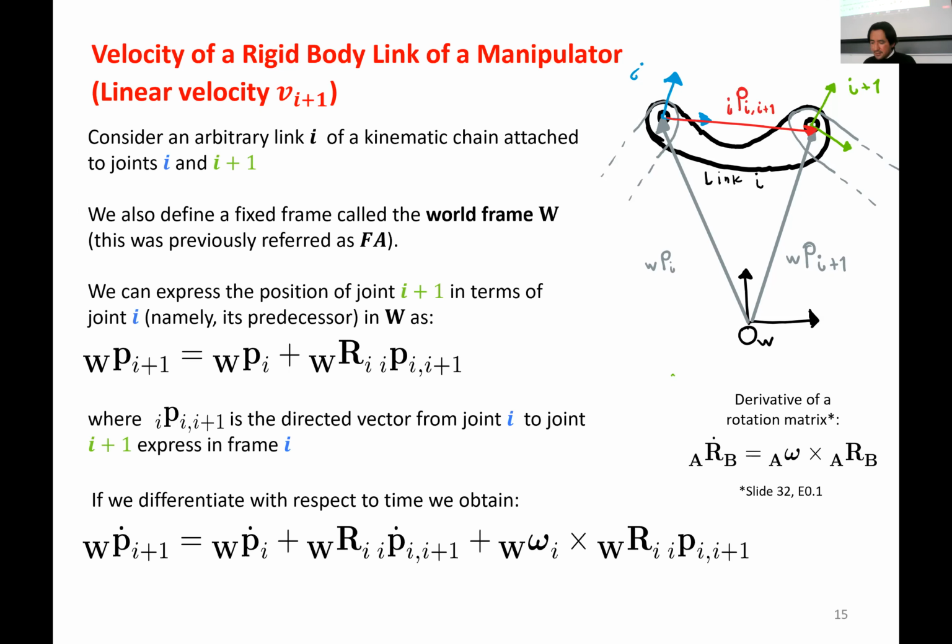The vector from link I, I would say, is constant in the link frame, moves with the link, and the origin is constant with the joint, the supporting joint. But I would say this is from link I to link I plus 1, because between link I and link I plus 1 there is the joint in the middle. That will create a motion, so we create this vector you're talking about. It's because we're referring to link frames, not joint frames.